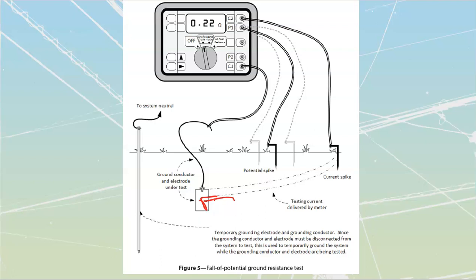You might have had a good installation, but then somebody decides that they're going to pave something, stick a sidewalk around the side of a house. I know for a fact that probably a lot of you have buried ground plates real tight to the side of a house, and then they put a sidewalk over top of that. What happens is all the soil underneath there over the next couple of years is going to get very, very dry. Dig up a basement sometime. If you ever dig up dirt that's been underneath a house, that dirt, for the most part, unless there's sideways seeping of water, is going to be relatively dry, which means it would be poor conductivity. So anytime stuff has been paved over or concreted over, expect that it's going to have dried out.